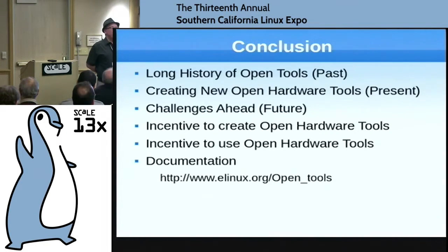The advantage to using Eagle with SparkFun libraries is you can go to SparkFun and say, I want this LED. I'm going to order 10 of them, and at the bottom of the page is the library for that part. That is a big advantage, especially for somebody that's new to hardware development and may not necessarily know how to create their own footprint and symbol. So if you go to SparkFun and you want to create a small board for your first time, you have the libraries to get started and get your feet wet. But I agree, there are tons of libraries. It just tends to not be connected. Say, here's the library part, and here's where you order this part, and get it together at one time.